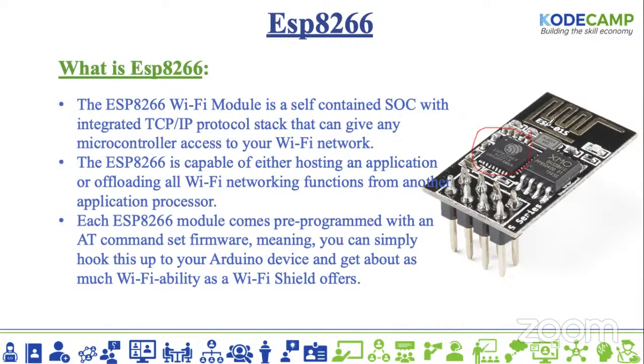This is the ESP8266 01S, and it has just about 8 pins, and then 2 for power. It takes just 3.3 volts. Please do not give it anything greater than 3.3 volts, because it's very, very sensitive.